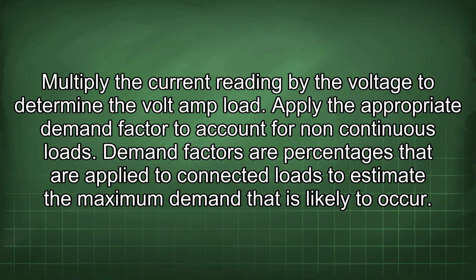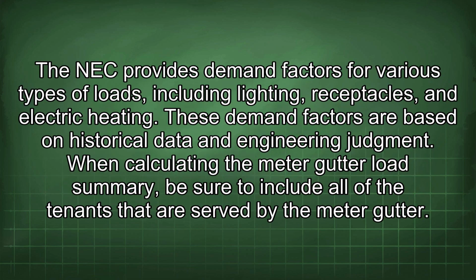Demand factors are percentages that are applied to connected loads to estimate the maximum demand that is likely to occur. The NEC provides demand factors for various types of loads, including lighting, receptacles, and electric heating. These demand factors are based on historical data and engineering judgment.